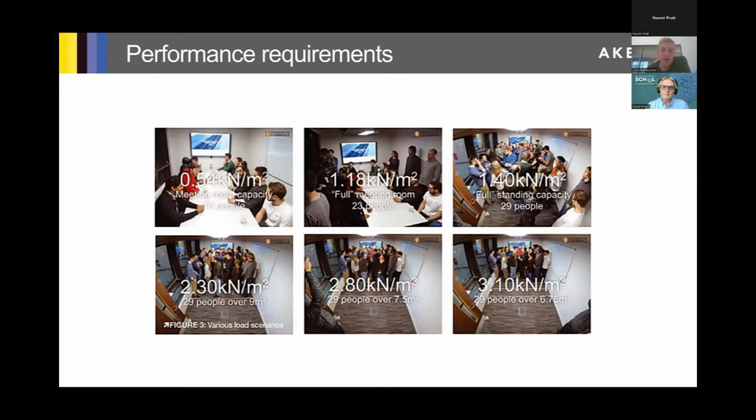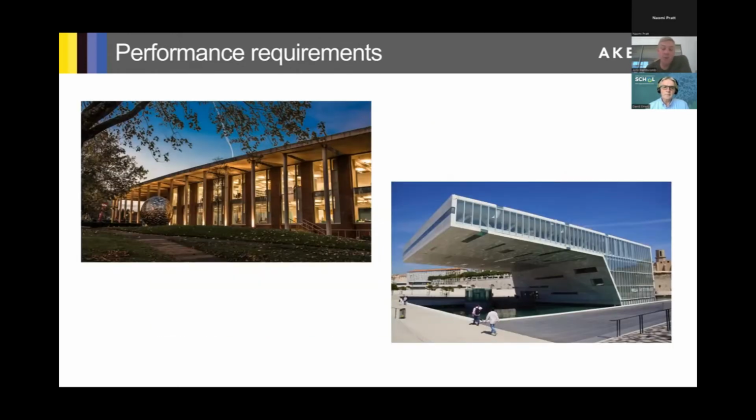So what are the floor loadings? Mechanical electrical plant, for instance, is generally getting lighter, it's getting smaller. How is that reflected in your design loads? Or are we just taking design loads that we used historically and not giving that thought? So we're looking at optimizing design loads can have a big impact on reducing the overall volume of concrete and the reinforcement.